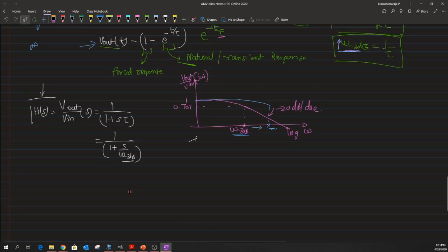And right now let me see how this bandwidth defines some sort of requirement on our circuit. Before I start doing that, there is one more point that I need to talk about over here. It's a term which is known as unity gain frequency. As I already said, it's the frequency at which the gain becomes 1, and probably I cannot use this circuit to talk about it just because I have assumed that the value of input itself is 1 and the gain of the RC network is already 1. So we cannot discuss that particular term over here.